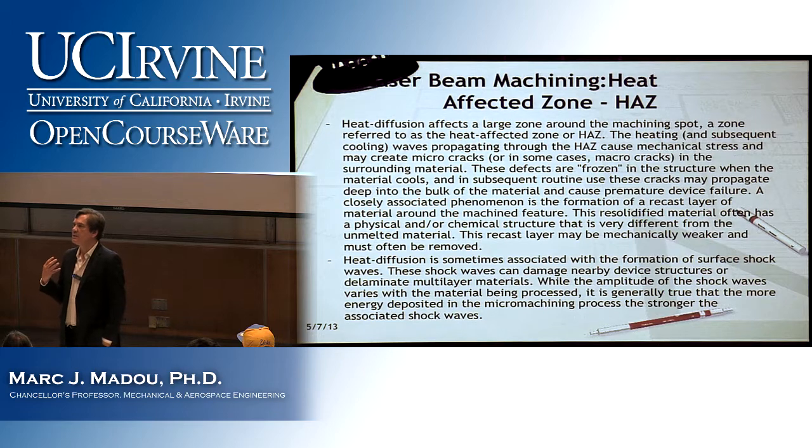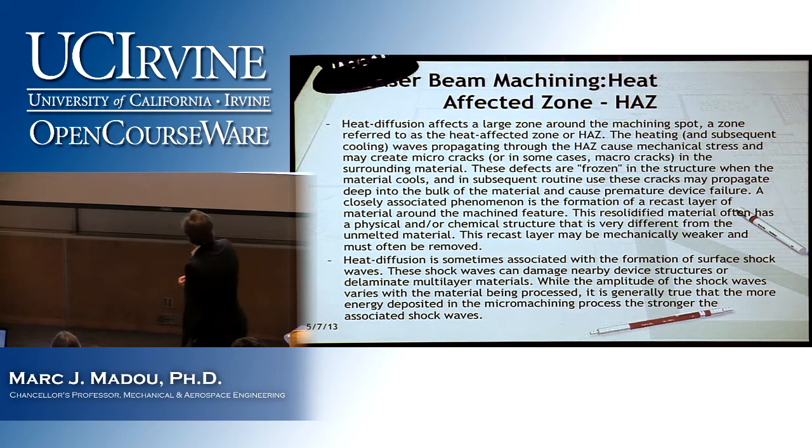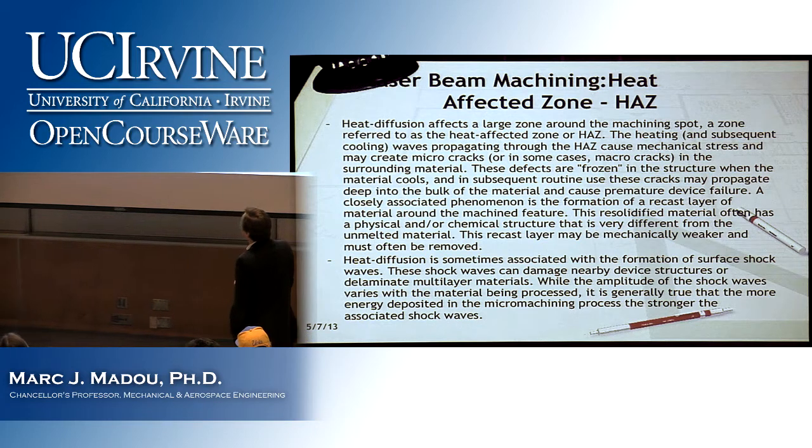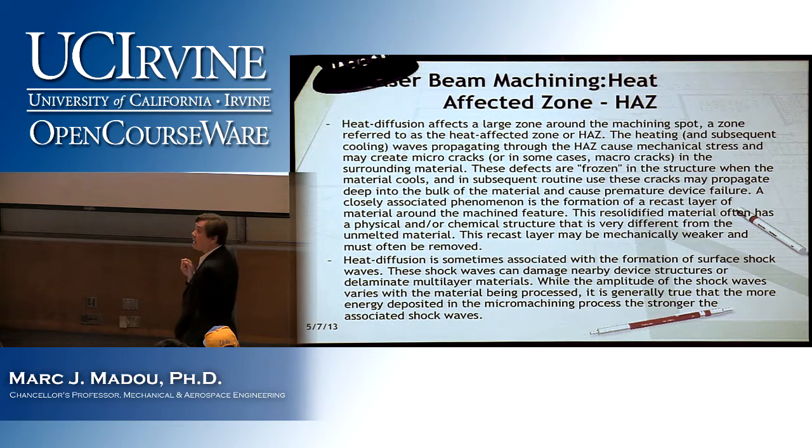Of course, this heat affected zone is not limited to laser machining. Anything that produces heat and machines via heat will have this effect. The heating and subsequent cooling waves propagate through the HAZ and cause mechanical stress and might create microcracks, in some cases even macro cracks in the surrounding material. These defects can then be frozen into the structure when the material cools, and in subsequent usage you might have the part actually breaking on you.